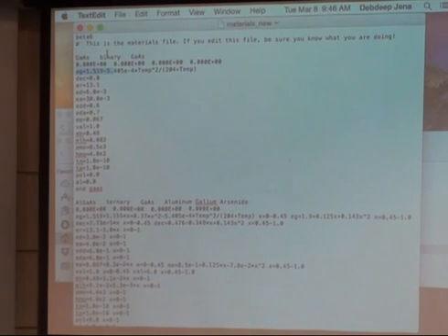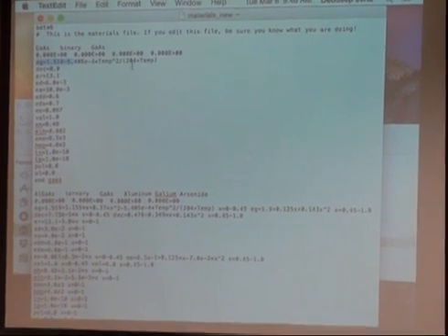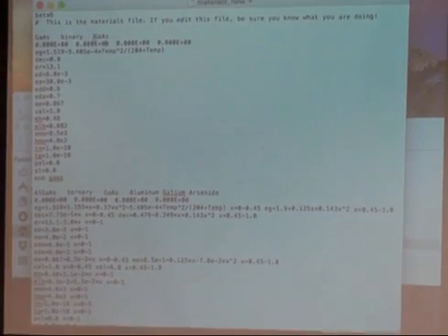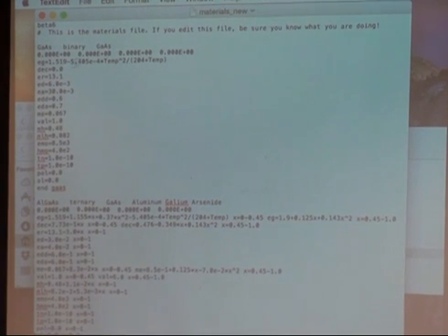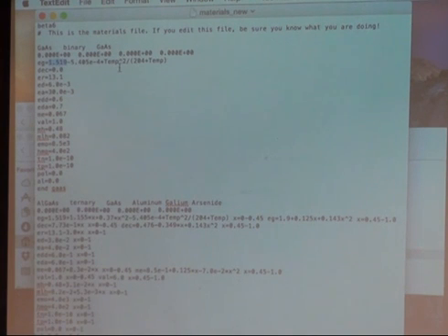So for example, gallium arsenide is a binary semiconductor, and so there's a formula for it. This is the zero temperature band gap, and as you change the temperature, the band gap shrinks a little bit. At room temperature, it's about 1.4 eV. And it has all these properties. The effective mass of electrons in the conduction band is 0.067. That's the conduction band effective mass for gallium arsenide, and so on. Heavy hole, light hole, all that stuff.